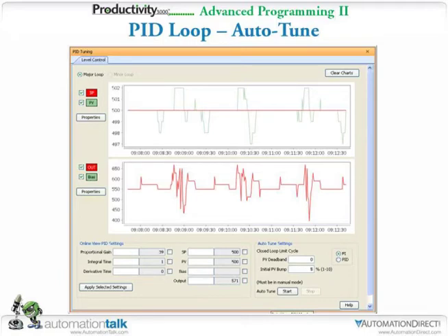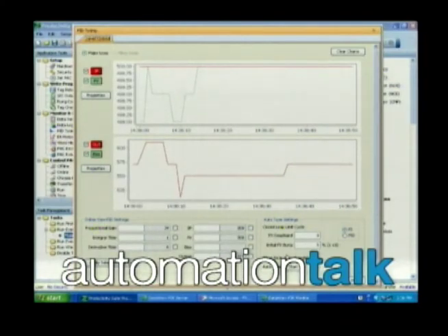I was really impressed with this because I had everything running and it was sitting there stable, and I put it in manual operation and I hit the auto tune start, and after 3 initiations of up and down, it found itself, and it actually came up with the value for the proportional gain and the integral time. This particular application derivative really wouldn't do a whole lot for because of the slow response and everything that's required. And I should mention the stack lights.